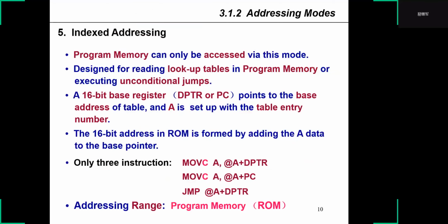Next, I introduce the indexed addressing. Program memory, which means ROM, can only be accessed by this mode. It is designed for reading lookup tables in program memory or executing unconditional jumps.